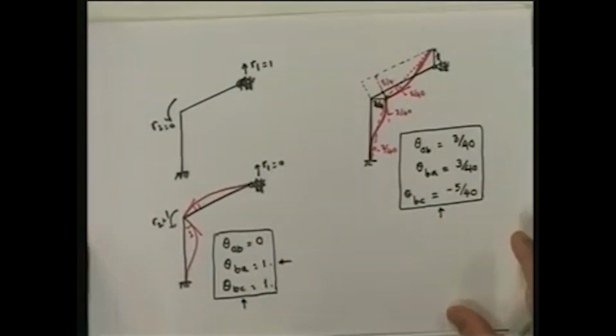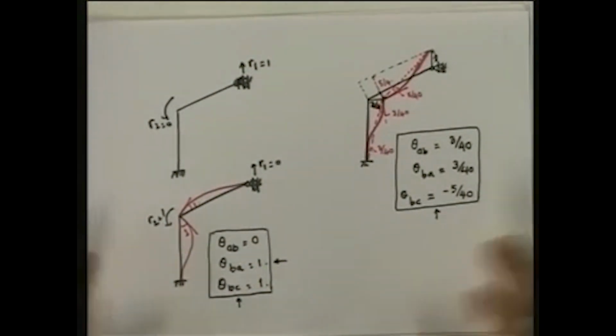Okay, so the point that I would like to make is that the kinematics definitely depends on the support conditions. However, if we change a fixed support condition to a hinged support condition and keep the geometry the same, it has no effect on the overall kinematics.